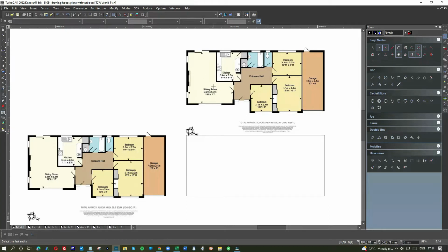So the outside walls on an old bungalow, most of them built in the 60s, would have a bit of a cavity, but no insulation. In the 1940s, 1950s, no cavity at all. It's just 2 blocks and a bit of rendering. So what we're going to do today is build on the basis of a cavity, as in a new bungalow. And a new bungalow would be 100 block, 100 of insulation, and 100 a block again. So therefore we're looking at 300. Basic thickness of the wall would be 300 for an outside wall.